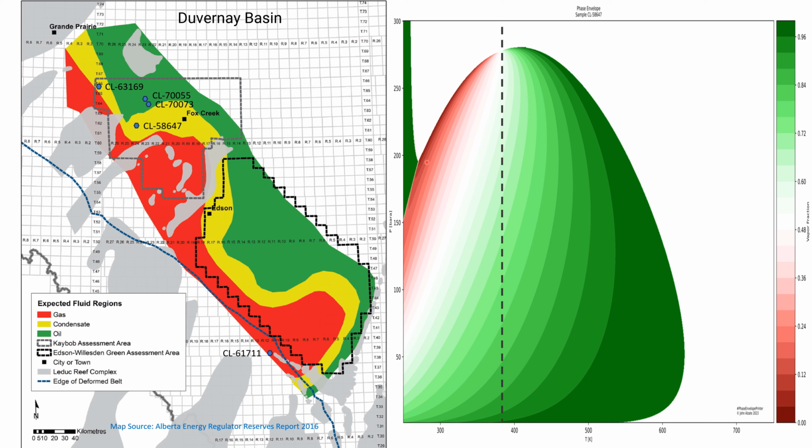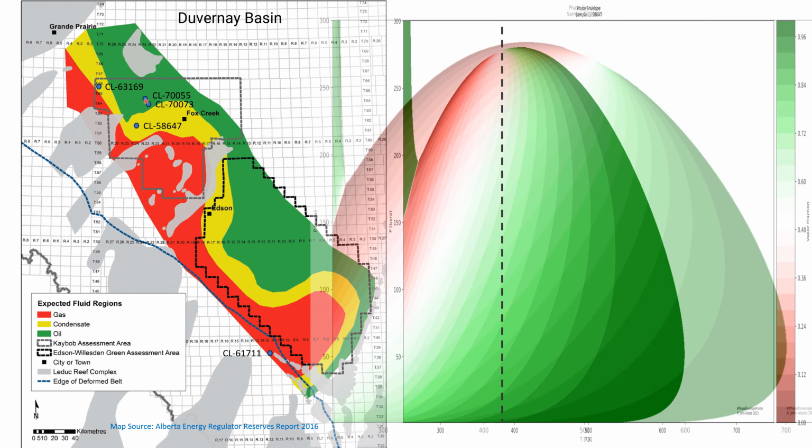Around 200 bars, again, we have an unstable tail, right? Shooting upwards asymptotically. At this point, I cannot tell you exactly what this tail is made of, if we have vapor liquid equilibrium or liquid liquid equilibrium or vapor liquid liquid equilibrium, but we know for sure this model predicts an unstable fluid in this region.